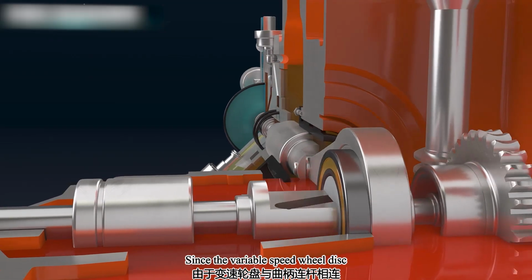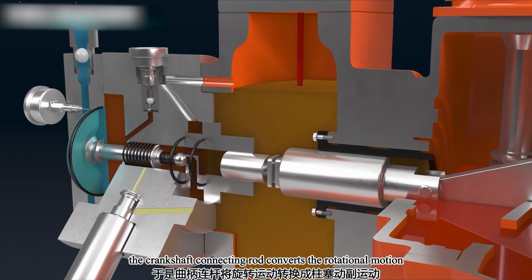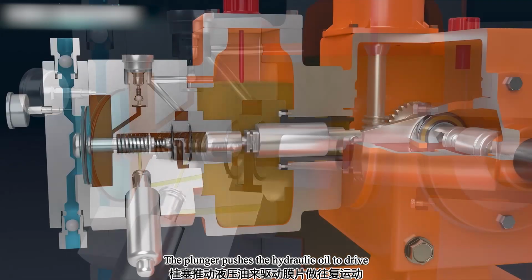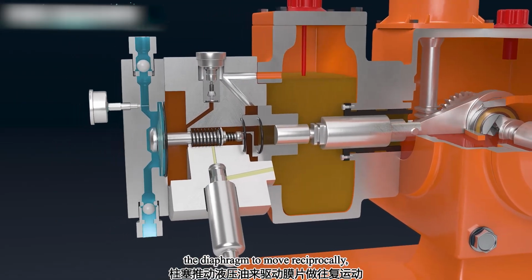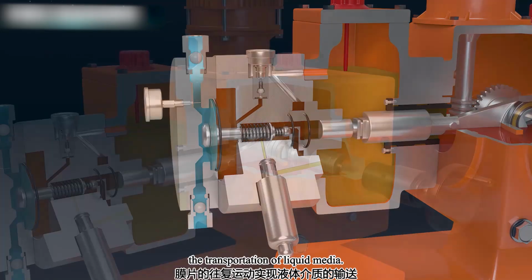Since the variable speed wheel disc is connected to the crankshaft connecting rod, the crankshaft connecting rod converts the rotational motion into the reciprocating motion of the plunger. The plunger pushes the hydraulic oil to drive the diaphragm to move reciprocally, and the reciprocating motion of the diaphragm realizes the transportation of liquid media.